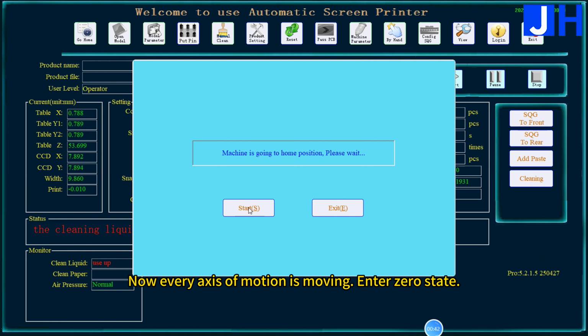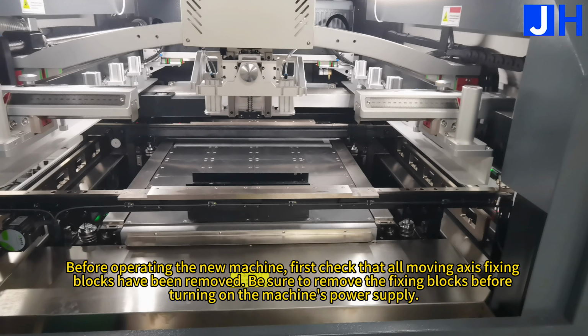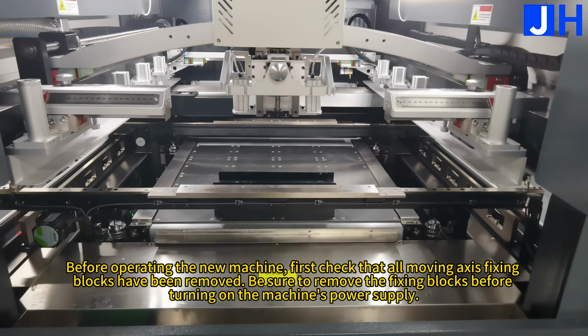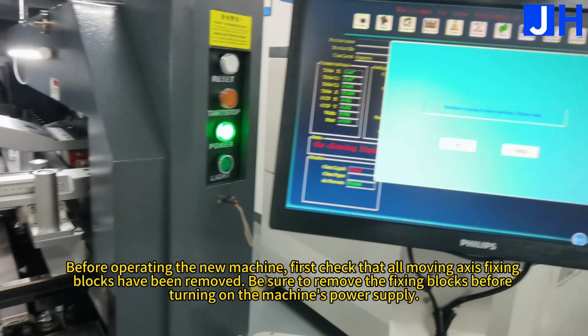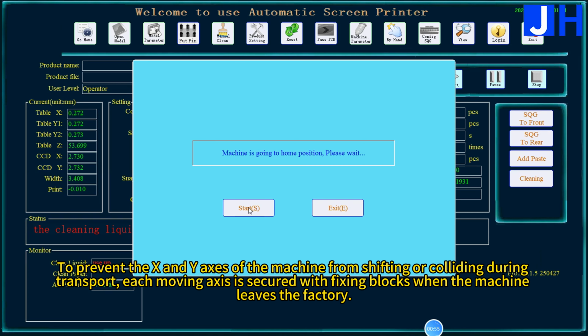Enter 0 state. Before operating the new machine, first check that all moving axis fixing blocks have been removed. Be sure to remove the fixing blocks before turning on the machine's power supply. To prevent the X and Y axis of the machine from shifting or colliding during transport, each moving axis is secured with fixing blocks when the machine leaves the factory.